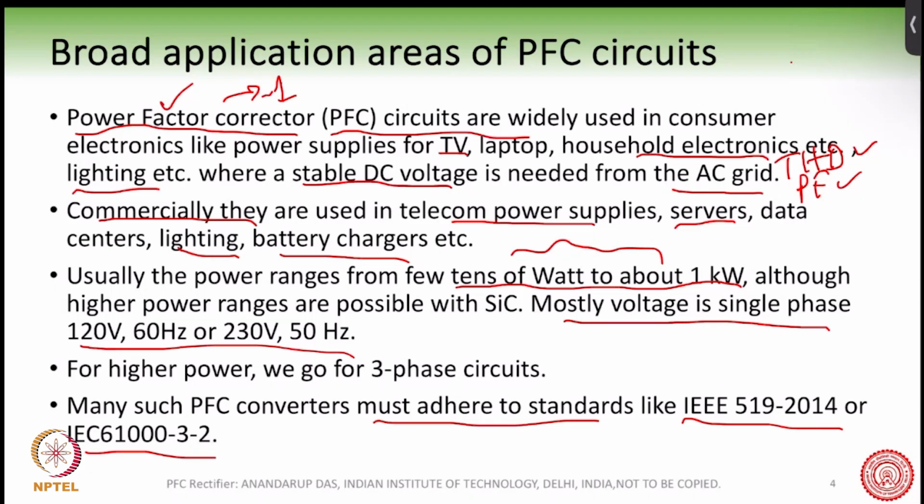In India, we have a 230-volt, 50 hertz system, but in some other countries like the USA, they have 120-volt and 60 hertz. One of the things that you have to remember as a design engineer or product builder is that sometimes we build PFC circuits which can be sold anywhere in the world. In that case, you have to design for both the voltage and the frequency level.